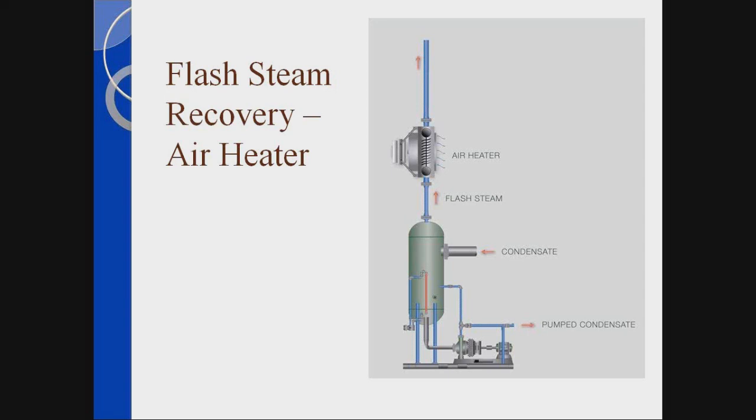But I'll give you an example. I was at a facility last week, in a cool area. It was down in one production area, and the vent for the condensate tank system was right there. By just putting in a simple air heater, as shown in this print, we can collect that flash, or recover that flash energy, and provide heat for the building, which they said is on for about 185 days a year. That is a lot better than heating the outside air, which is no use to anyone. So this is just another way of accomplishing recovery of the flash steam.